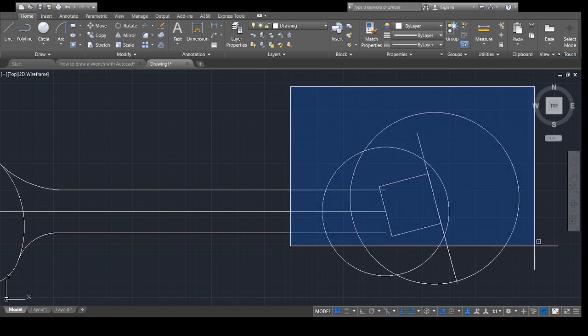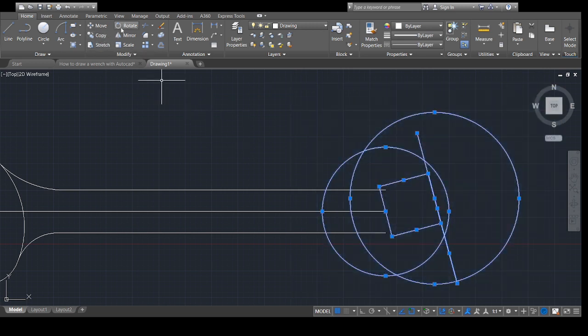So you can select the object, then select trim, and then trim this, because this other end is the bigger circle end, the other side is the smaller circle end. So remove the smaller circle from this side, but you're not going to remove the rest right now, because if you do that, there will be a line that will be lost when you are going to do the fillet. As you can see, for example, if we did that